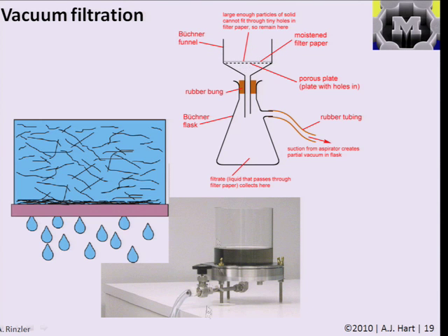So, like shown here, you draw the water, the solvent, through here, and you leave the nanotubes on top. If you controlled the concentration of nanotubes in the solution and the amount of liquid you drew through, you could control the thickness of this film. And because you have a uniform pressure across this membrane, you can probably get pretty large area, quite uniform films.